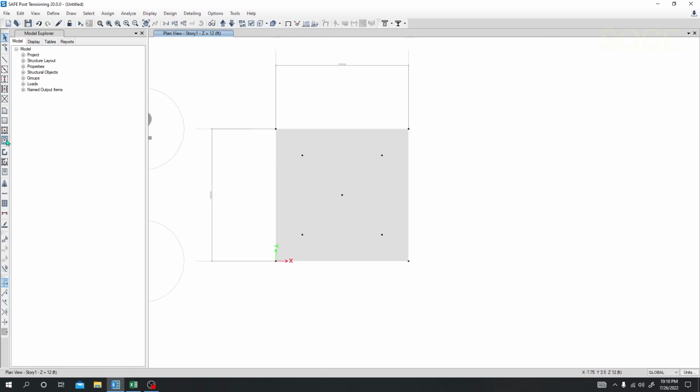Now I'll go here, draw quick area around the point, and I'll take pile, and what will be our pile size? So what is the shape of your object? That is circular. And what was our pile diameter? That is 20 inch, right?